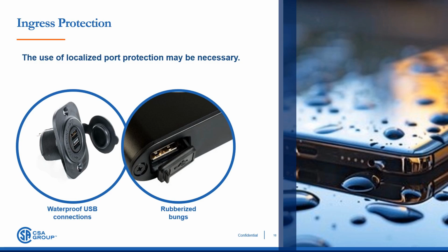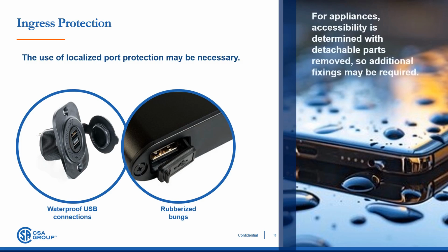However, unless a tool is required for removing such covers, these additional port protections are unlikely to help with determining accessibility, as accessibility is determined with detachable parts removed. Consideration of moisture and ingress protection into the interface in all positions of normal use when connected is still required. This may necessitate the use of specialized fixed terminals, locking or screwed interfaces, or other suitably environmentally protected interface enclosures.